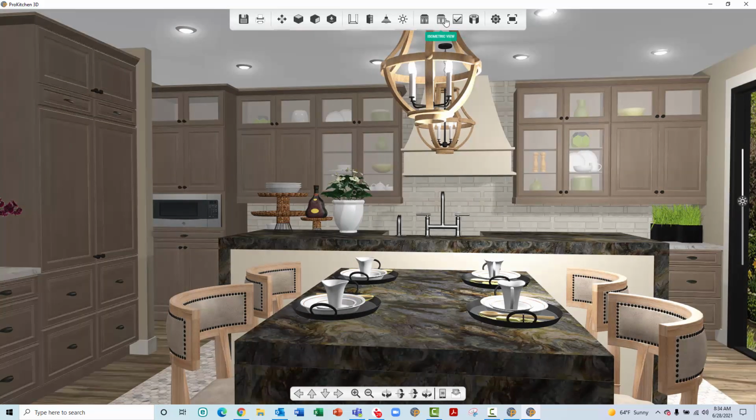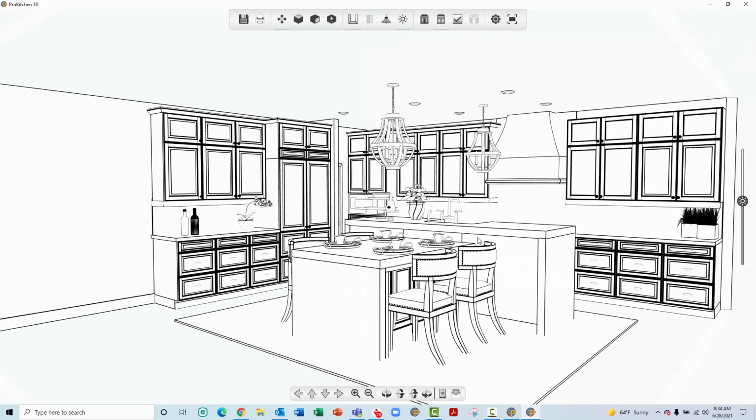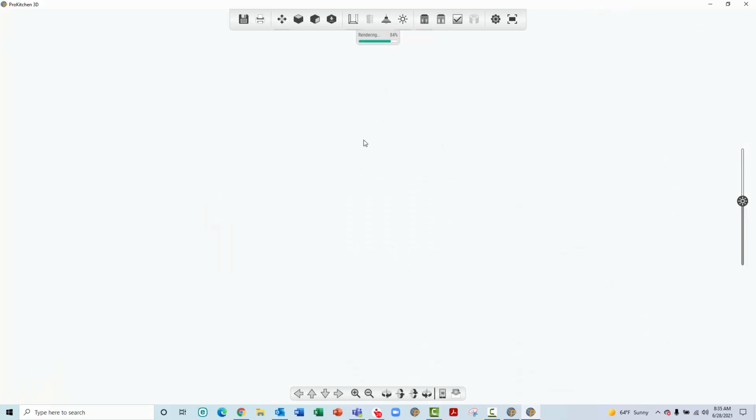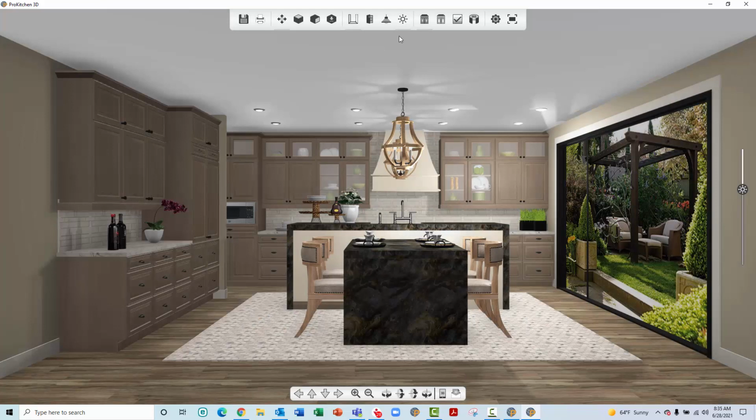Use the 3D View isometric tools to switch between color and black and white. While in isometric view, left-click the Refine tool, and Pro Kitchen will create more dimension with occlusion shadows and highlights to create a sketch type rendering of the design. When in full color 3D HD and left-clicking the Refine tool, it will enhance the HD quality of your image, increase the realistic shadows and reflections on metallic-like or high-sheen objects.